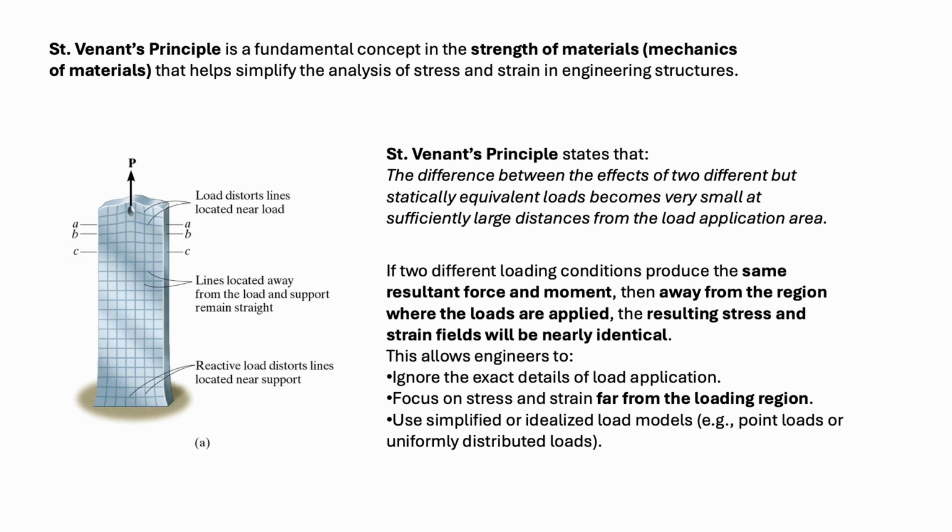So St Venant's principle states that the difference between the effects of two different but statically equivalent loads becomes very small at sufficiently large distances from the load application area. If two different loading conditions produce the same resultant force and moment, then away from the region where the loads are applied, the resulting stress and strain fields will be nearly identical. So this gives you the opportunity to ignore the exact details of load application, to focus on stress and strain far from the loading region, and to use simplified or idealized load models.